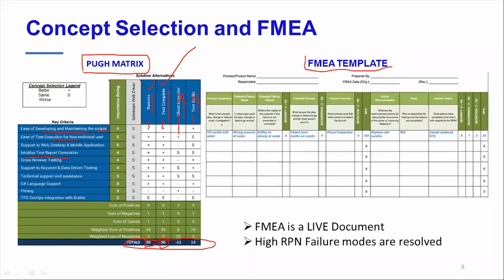you have your failure modes listed. Let's say, for a tank, the failure mode is that it bursts. Why would it burst? Here it is the fuel tank, and it bursts. Now the fuel tank may burst when, let's say, the tank has fuel. If it is hot season, the fuel also gets vaporized.